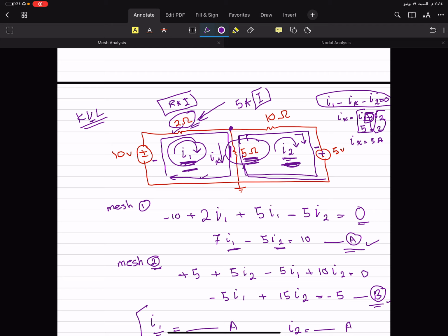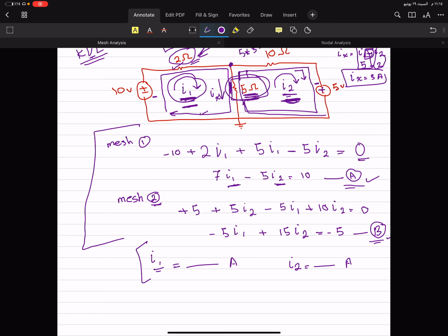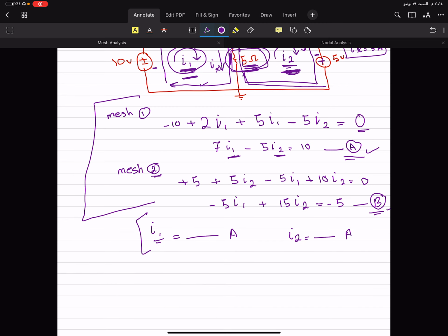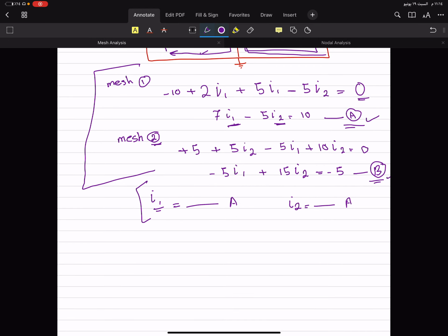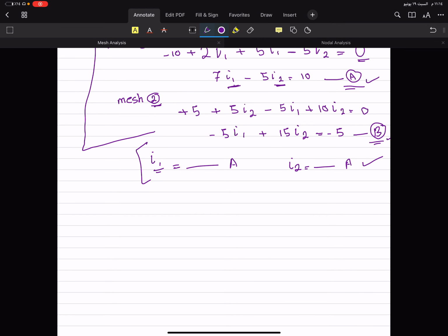It's very easy. Then you have the current of Ix. This current is the current passing through the 5 ohm resistance, which is this one, Ix. So the voltage across the 5 ohm resistance will be 5 multiplied by Ix, which I assumed equals 3, so it's 15 volts, okay? This is just an assumption, the numbers are not actually true. Solve it in a system, then you can have the answer, put it here, and test yourself.